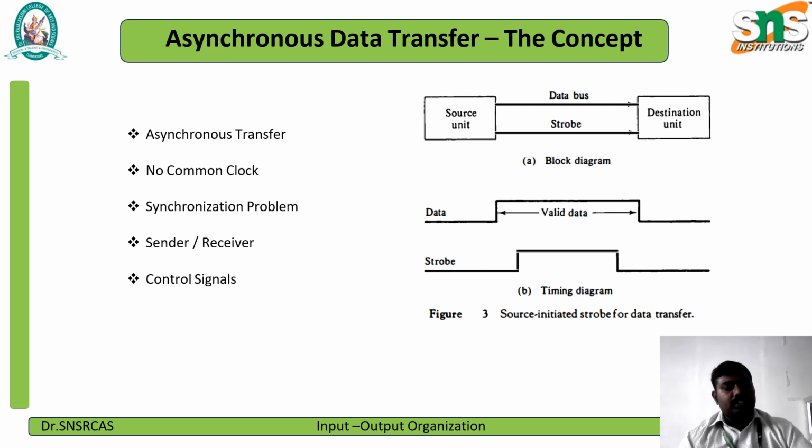The advantage of synchronized data transfer is that the design procedure is easy. The master does not wait for any acknowledgement signal from the slave, and the slave does not generate an acknowledgement signal. Obviously, the timing rules are as per the protocol set by the master or system designer.